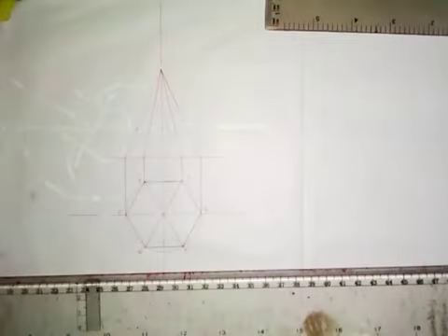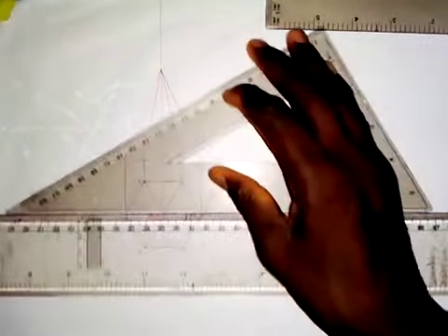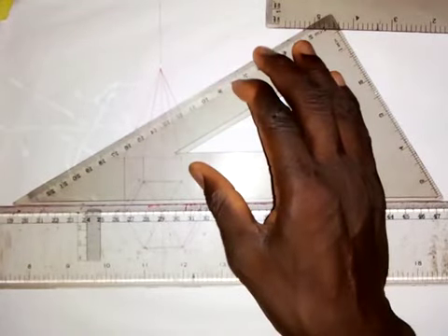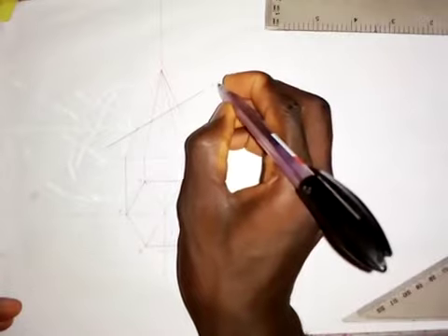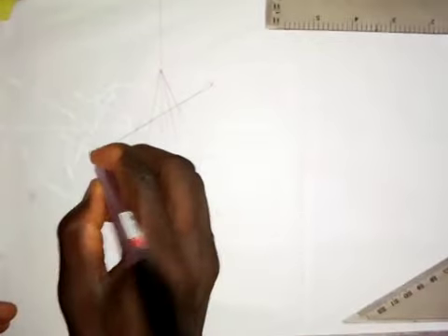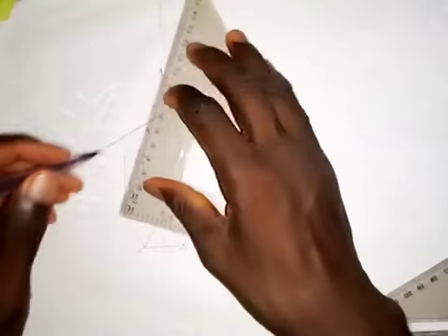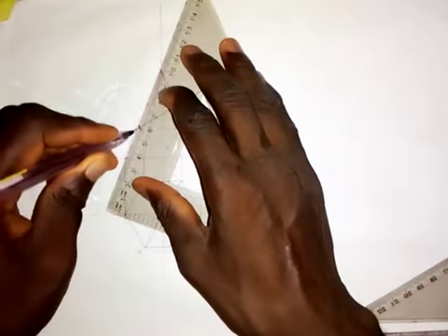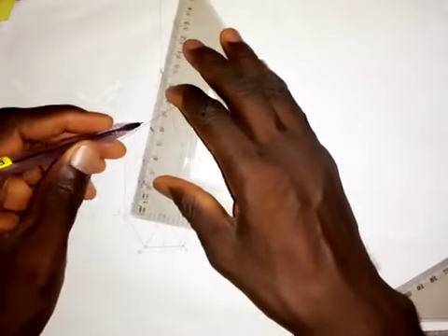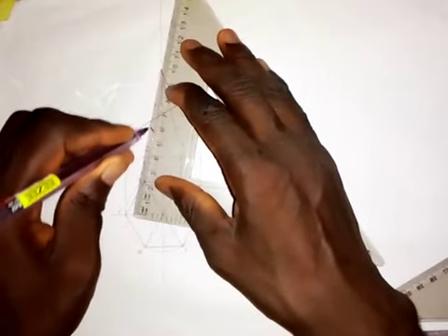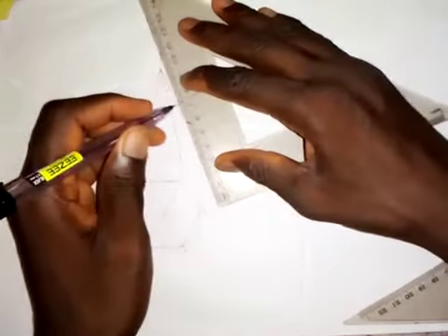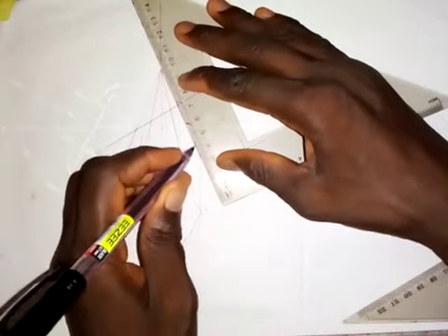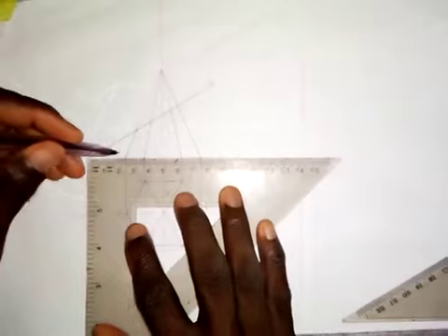So the next thing to do is to take my 30-degree set square like this and set it at this point. Then I will draw the cutting plane QQ as given in the question. So this is the cutting plane QQ. So this point is point Q, and this is also point Q here. So the next thing to do is for us to make this a thick line. So this part has been cut off. So then you also make this a thick line. Next, you make this a thick line, and also we make this a thick line here. And then we are going to make the base thick.